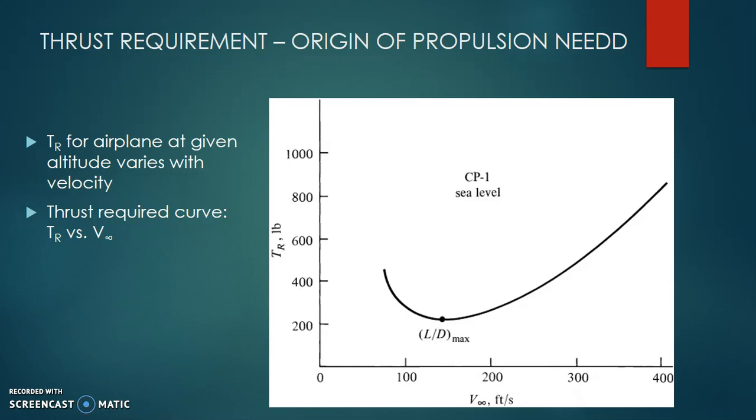So the excess lift actually causes it to go into a circular path, or to ensure that it doesn't go into a circular path, you have to adjust using your flaps and your ailerons, and therefore that additional lift, because of these high velocities, is not very optimally useful. But drag is always a penalizing drag. No matter what you do with lift, it says, boss, my job is to penalize you. With additional velocities, in the regimes of higher velocities, drag increases. Hence, to match it, the thrust required keeps increasing.